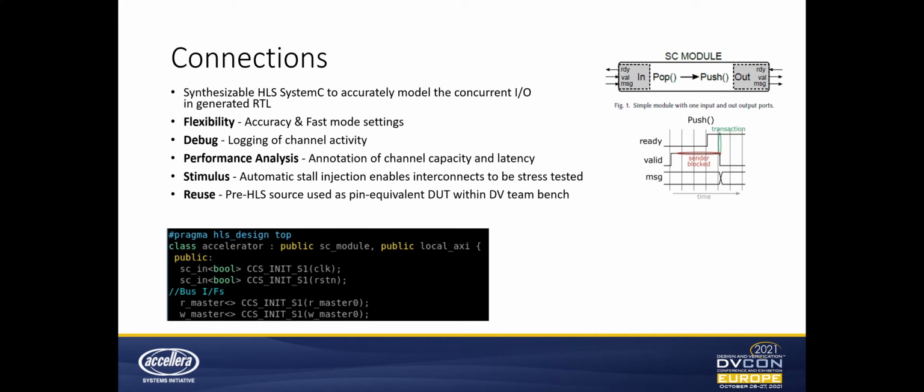The performance benefits themselves have some controls associated with them. You can choose between a cycle accurate mode, which more closely models RTL latencies, along with a fast mode, which trades accuracy for more speed. The accuracy mode simulation is going to typically be a good deal faster than RTL simulations, and the fast mode can often run a good deal faster beyond that.